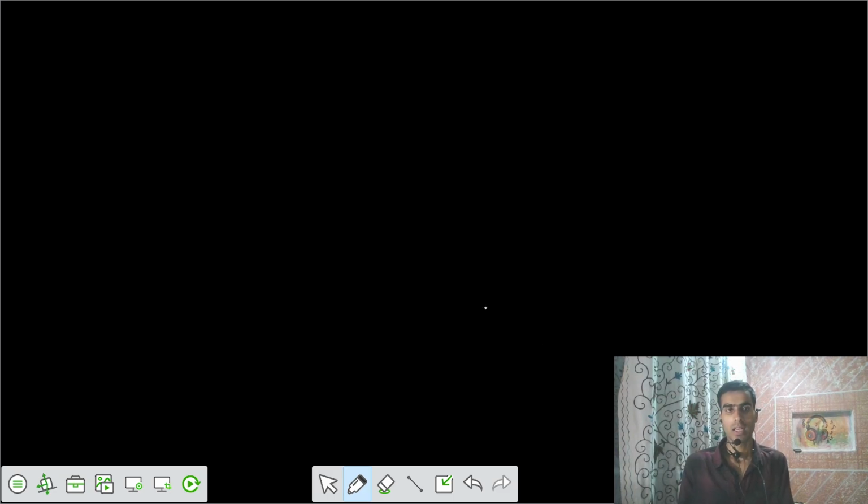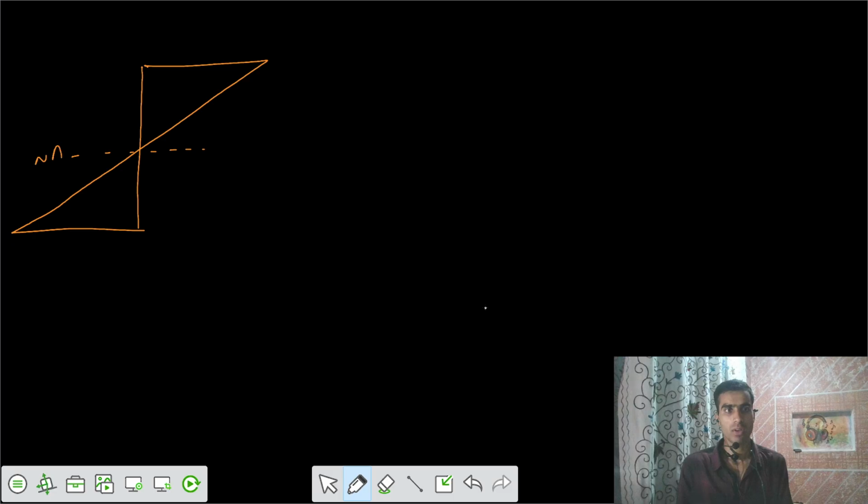Let's go for that. Once we have those assumptions, let's put them in a picture now. I would say there's some neutral axis, and there's a strain value of 0.0035 at the top extreme fiber as per assumption 2. Based on the diagram of the stress-strain curve, we had assumed that the variation is parabolic and after that rectangular.